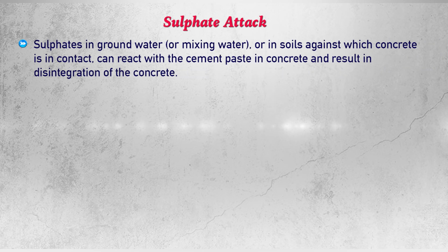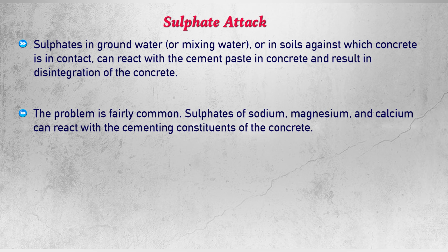Now, let us move to sulfate attack. Sulfates in groundwater or mixing water or in soils against which concrete is in contact can react with the cement paste in concrete and result in disintegration of the concrete. The problem is sulfates of sodium, magnesium and calcium can react with the cementing constituents of the concrete.